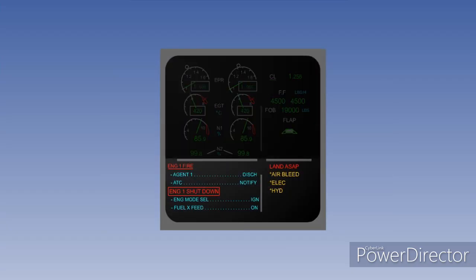The basic purpose of an integrated flight warning system is to prioritize all alerts so as to improve a crew's situational awareness. It achieves this by producing different types and levels of alerts relevant to the stage of flight, thereby ensuring that the crew tackle the warning posing the most immediate threat to safety.